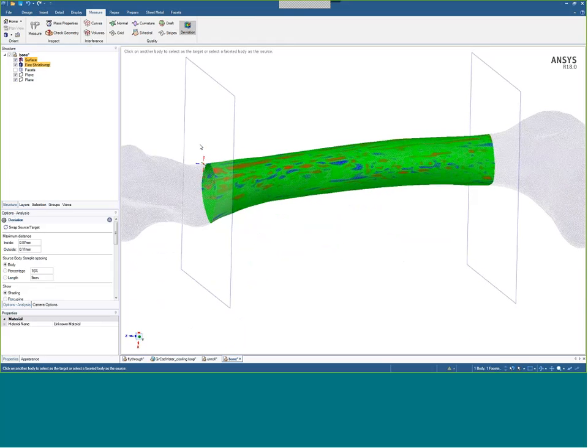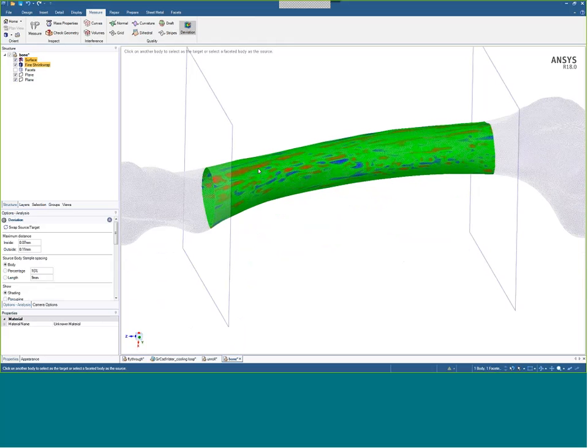What you also notice is it shows you a lot of the areas in red and blue where it's off. But just to highlight the size that is off, the maximum inside is 0.07 millimeters, and the outside is 0.1 millimeters. How can it possibly be so close, Roman? Well, it's using a ton of sample points as it's going through. It's essentially using 50 sample points, comparing that and laying that onto the model.